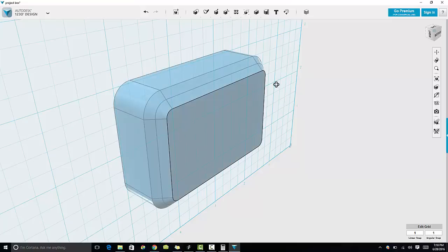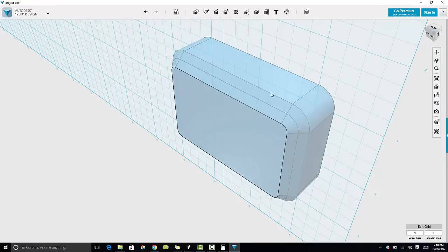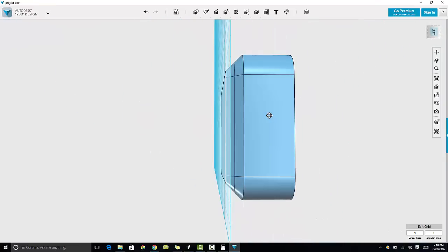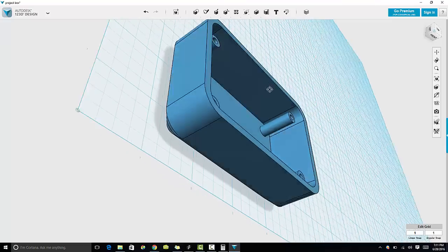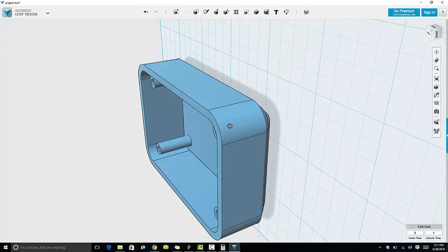And it also serves another purpose. When you guys are printing, if you chamfer your edges like this, most of the time you get better adherence. If you're using a heated bed and your bed is made out of that borosilicate glass, and then it has the heated element underneath it, or however you do it, if it's with a heated circuit board or whatever, the chamfered edges like this actually prevent the 3D print from lifting up off the bed very easily.